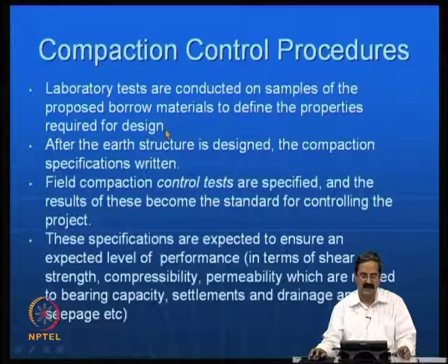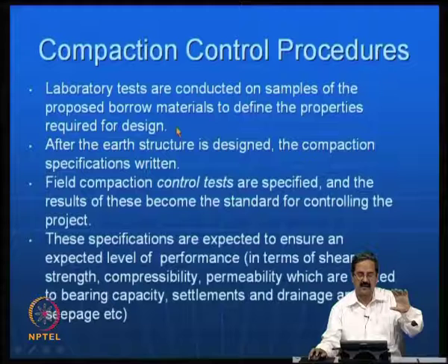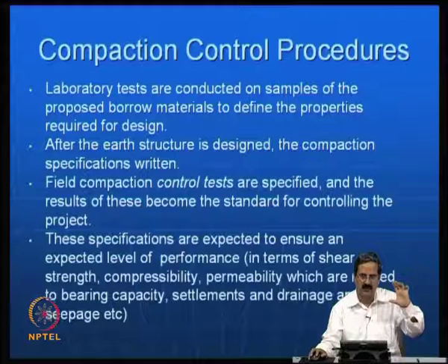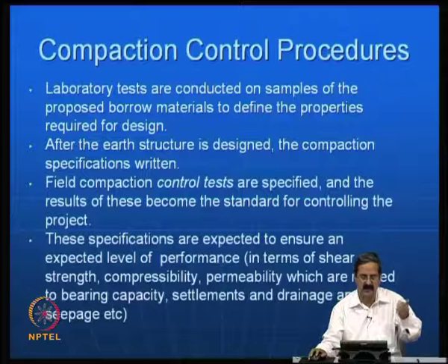What I mean is that you have an expansive soil layer and you do not want a load coming directly onto the expansive soil. So, you have a cushion on that. For example, some specifications say that a cushion of about 0.9 meters is required on the expansive soil, so that you are not directly in touch with the expansive soil.